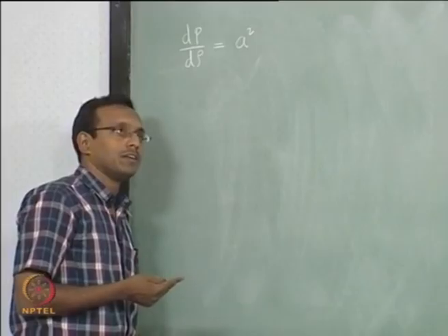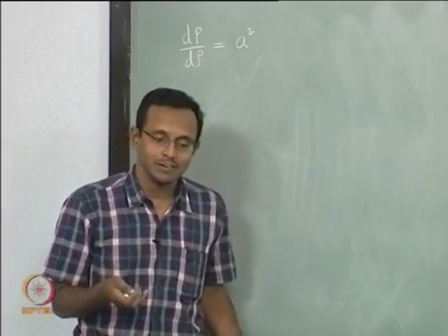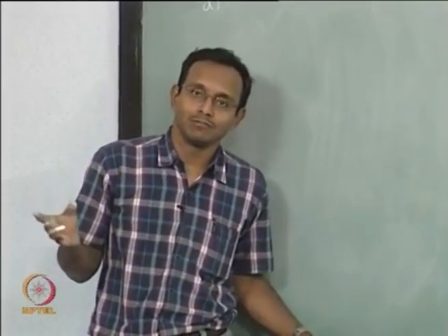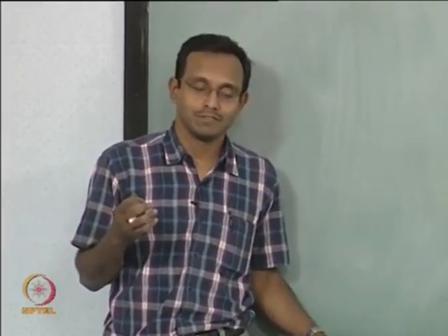We gave the argument in speed of sound derivation that my wave does not change anything in the flow, it does not change pressure, it does not change density, it does not change velocity, it does not change anything, then it is my sound wave. Okay. And that is the particular wave which will travel with speed of sound really. But this is not really a wave which does not change anything, it actually changes the velocity, pressure, density, temperature, everything. If it is changing, can I still use that argument? We are going to use that argument.